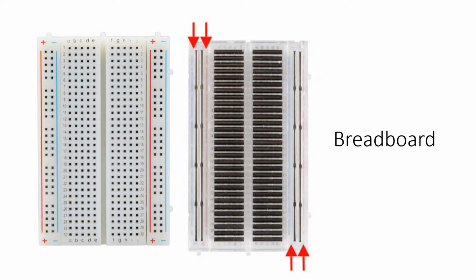What we've done on the right hand side here is pull off the backing so we can actually see inside the breadboard. What you can see in this first row is that this black is showing you that these are all connected. So connecting a resistor from, say, F1 to either E1, D1, or C1, it's all the same because these are essentially one point, but you're able to use different holes to connect them to the same point.